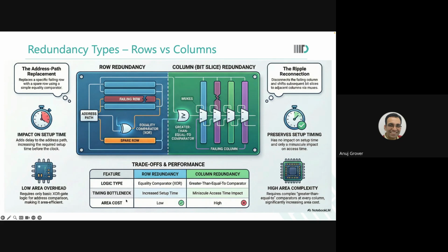Now, if two columns fail, or two independent defects come on the right side, you can't recover that. But that's not the spec. The spec for memory is one defect, or at most two defects. So I would want to go by the spec that the technology gives, because that's the target that they have. Because if I start to go beyond that, I degrade the PPA. So this would come to you as a specification.